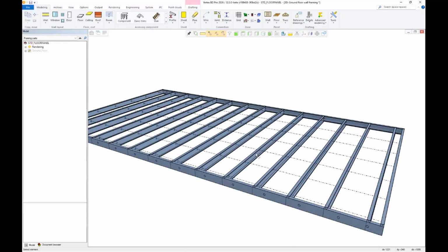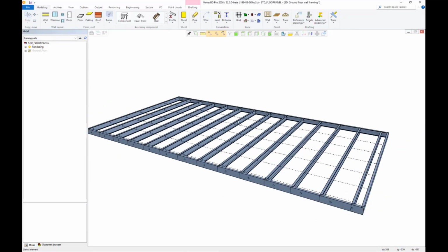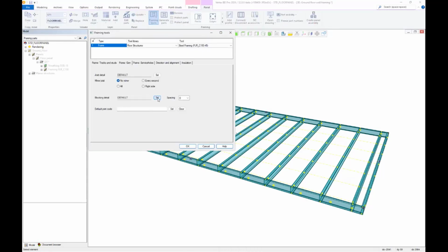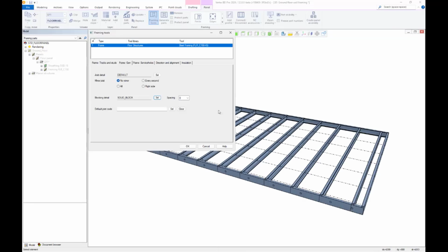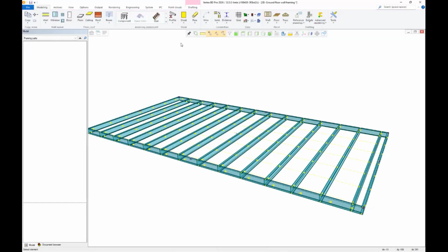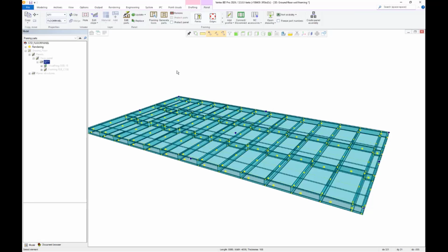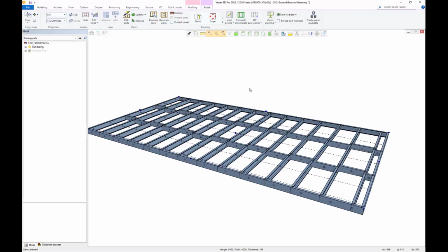If you want to set up the blocking, you can do that within the framing tool, under Framing, General, and the Blocking Details section, where you can hit the Select button to choose from your available blocking and spacing, and then regenerate your parts to apply your blocking, including service holes. Making this available in the Frame tool saves a lot of time when creating service holes for your builds.